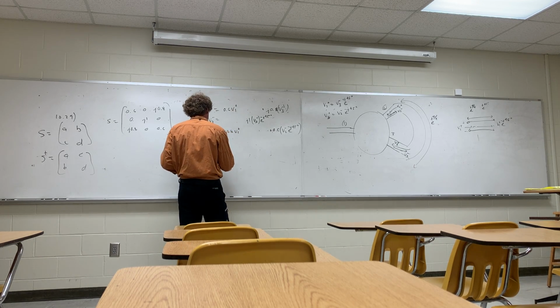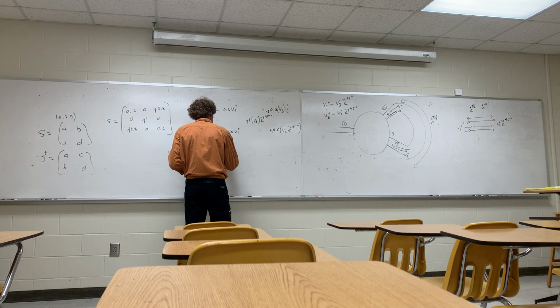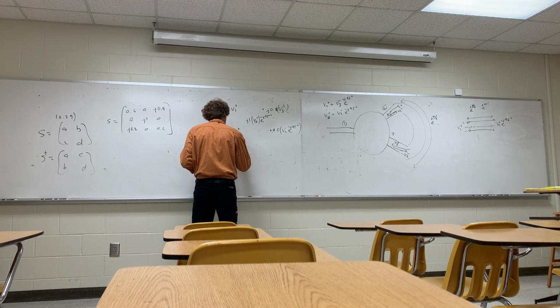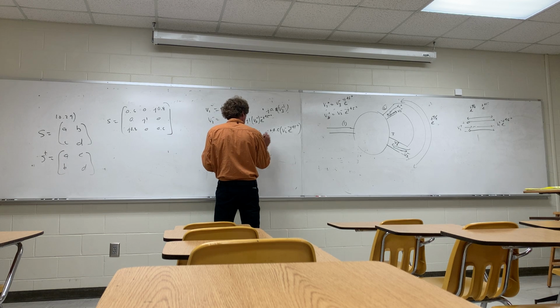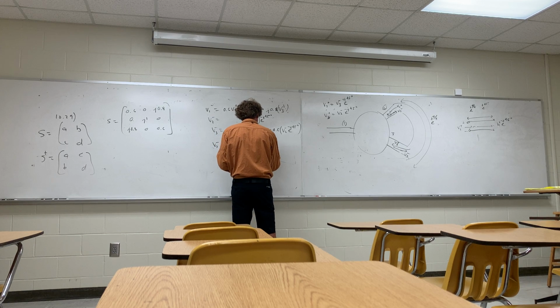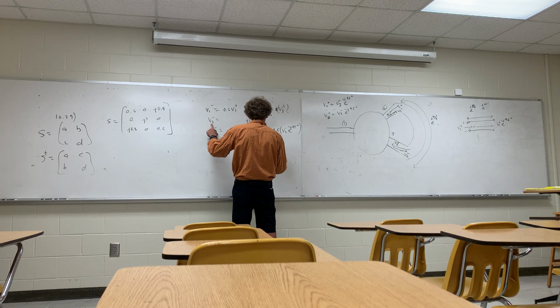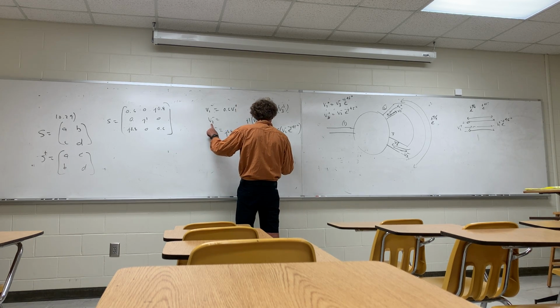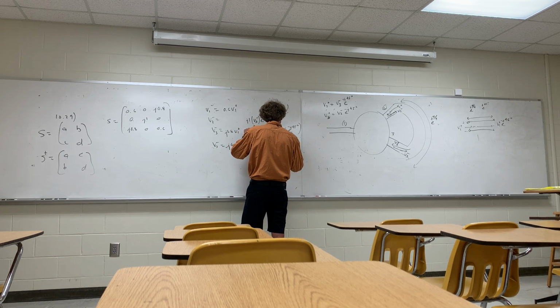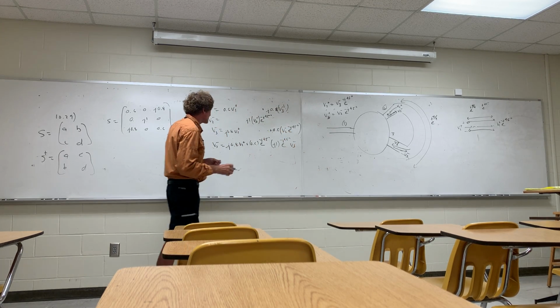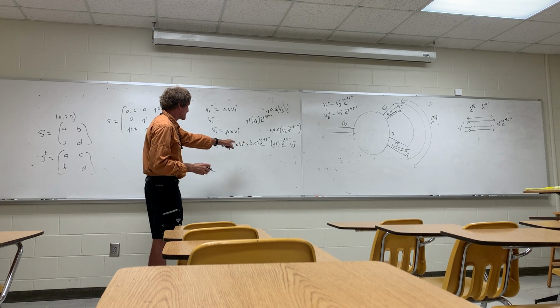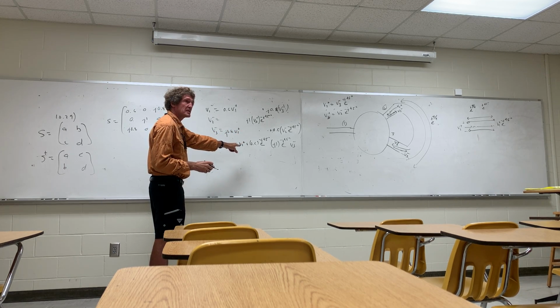I'm gonna try to do it right here. So I have V3 minus is equal to j 0.8 V1 plus. And then I come over here, it's plus 0.6 times e to the minus j 45 degrees, and V2 minus, which is going to be this, j1, this is going to get interesting, times e to the minus j 45 degrees, times V3 minus. Now the reason I did this is, now I have V3 minus in terms of V1 plus. Do y'all follow me on this?